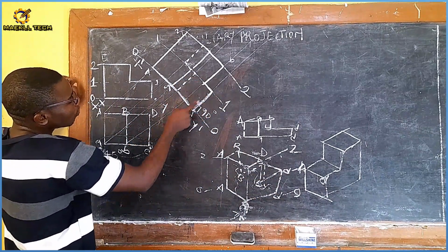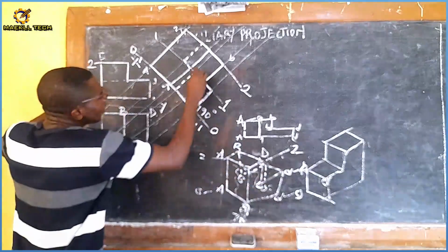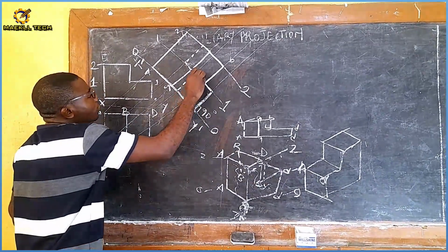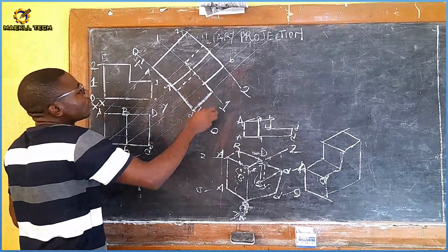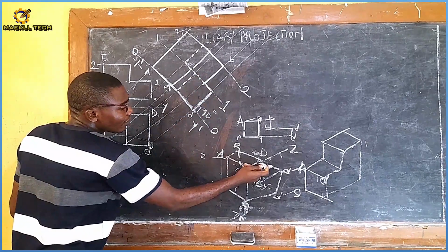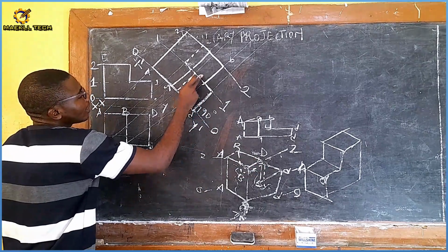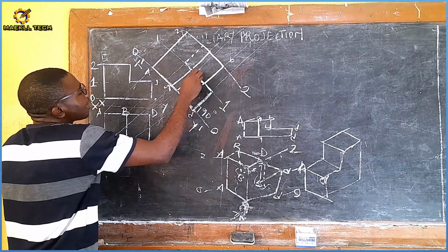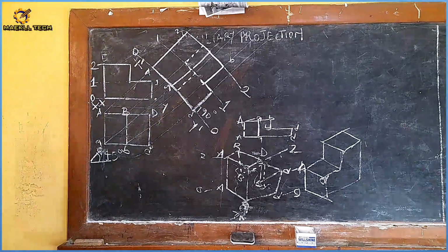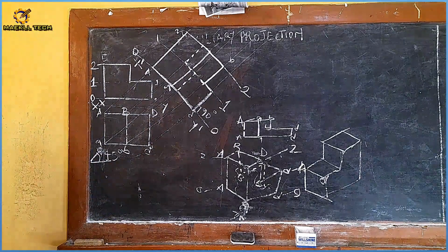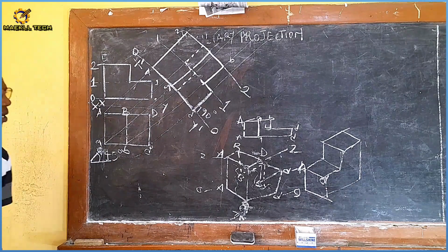And this is my small letter D. They connect to each other. So right here, I am doing it on the board. I will join it with a hidden line, because I can't see part of this area at the back. It will be with a hidden line. And that is the solution to this very problem on the screen.